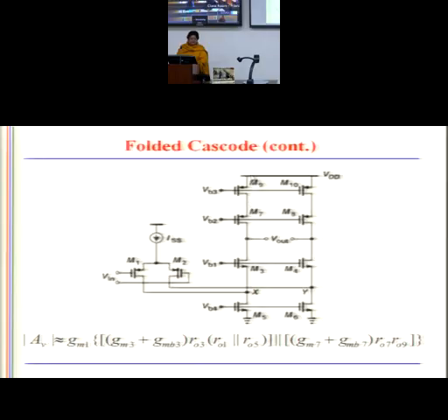At this node, looking at the drain of PMOS up, it is RO; looking at the source of PMOS down, again RO. Rather it would be RO parallel RO, because at this node it is actually RO parallel RO coming up. You have to make appropriate adjustments. So find out the pole. This pole and this pole will be non-dominant, whereas this will give you a dominant pole.